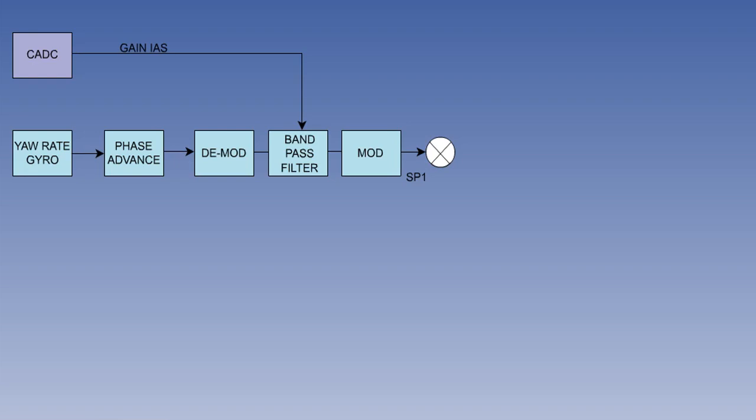The signal now arrives at summing point 1, labelled SP1, which also has an input from an inverting integrator, int1, which cancels any signals from the amplifier until the system is switched on when relay 1, RL1, becomes de-energized.